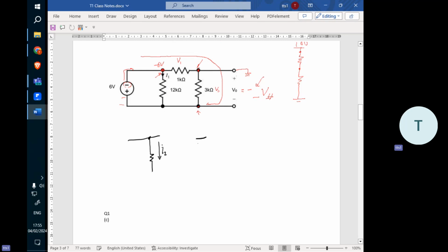And at the end, after some calculation, you find out that the current is, let's say, minus 2 ampere. So what does it mean? 2 ampere is the magnitude of the current, how strong the current is. Then this negative sign tells you that your current is actually opposite. Your actual I2 is opposite here because it's a minus. It means the current you defined like this should actually be like this. So if you follow I3 here, I3 should be equal to 2 ampere like this.